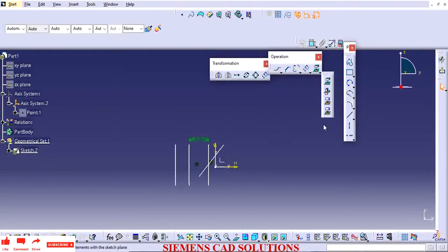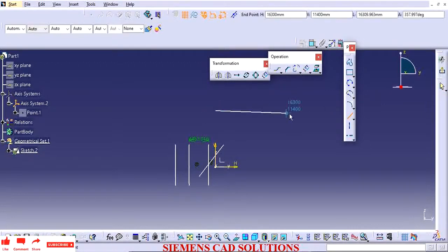So this is projection. This will be helpful while doing remastering. I will tell you while doing the remastering of the part. Apart from this, we have covered all these required features. Here we have one more option, grid. If you click on this snap to point option, your profile will move only on the grids.